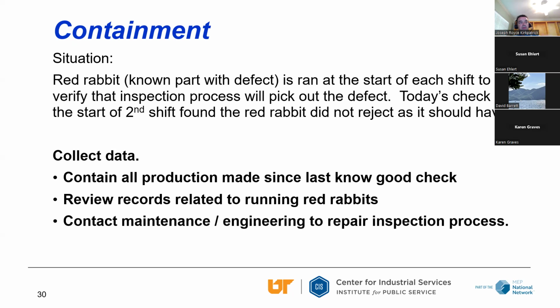Here's another example. Some companies have red rabbits, that's error proofing masters that they run at the start of the shift to verify that the inspection process will work. In this example, we had a check today on second shift, and their red rabbit, their defect part, did not work the way it was supposed to. So the inspection system is messed up. So we should collect all data.